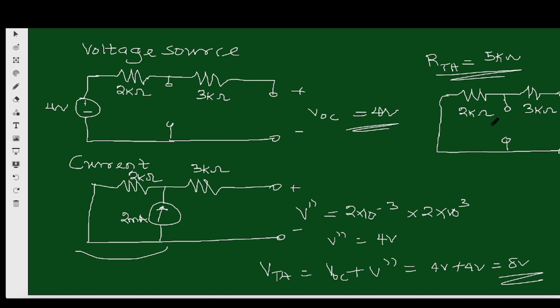And of course, you can now draw your circuit, and you can see that it's very, very simple to get the Thevenin's equivalent circuit and the Norton equivalent circuit. I used 2 methods here, the superposition method and the source transformation method. So you can use any method of analysis to get your Thevenin equivalent circuit and Norton equivalent circuit.